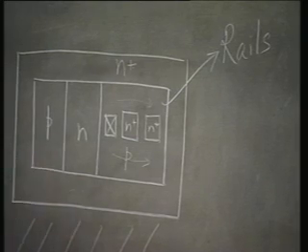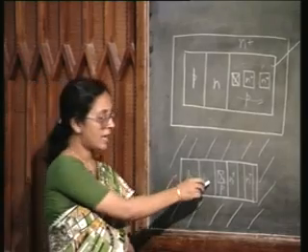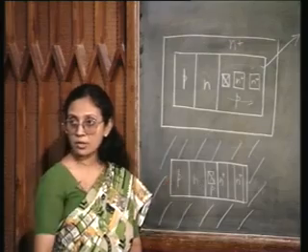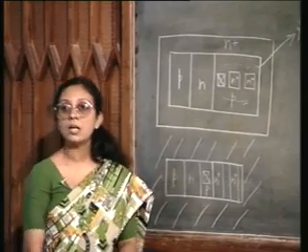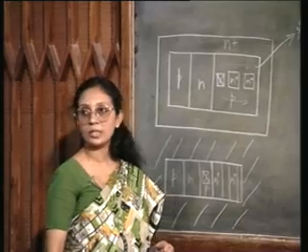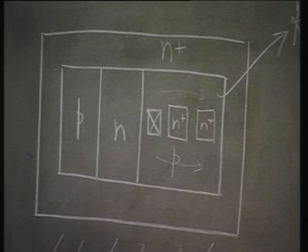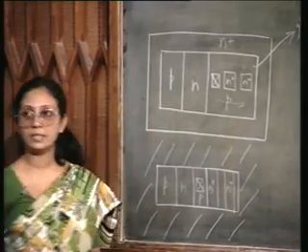So, as is obvious if you compare these two mask designs, I have a lot of space saving if we use an oxide isolation. Just compare this with this. I can achieve the same using a much smaller region. See, finally everything is determined by your lithographic limitation. So, it depends on how small an N plus region you can have. Here you must have a separation, here you do not need to have a separation. Therefore, the dimensions of this can be much smaller than in this case.